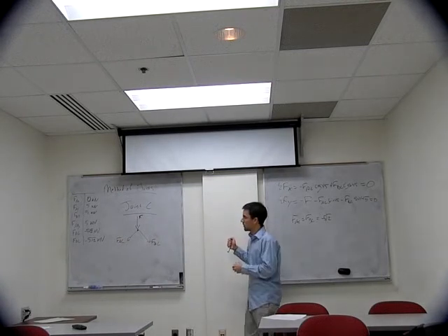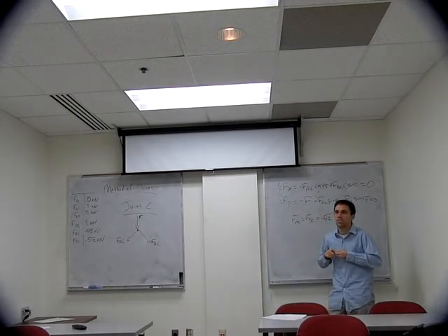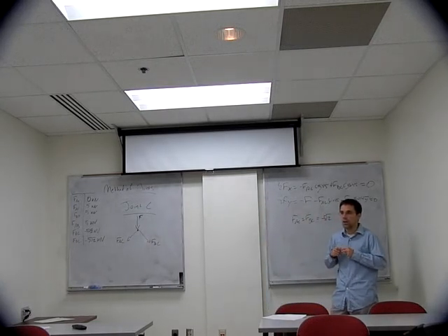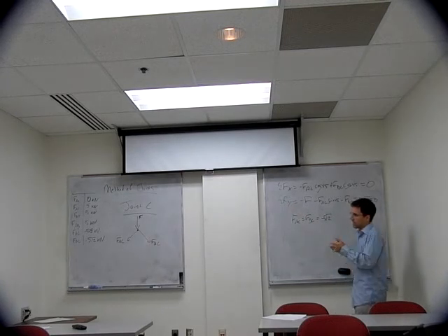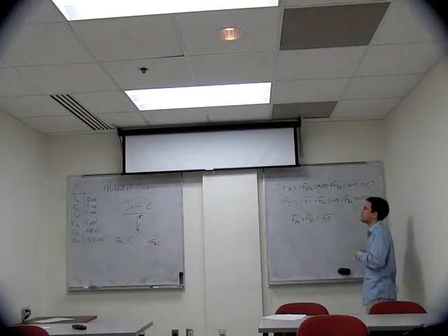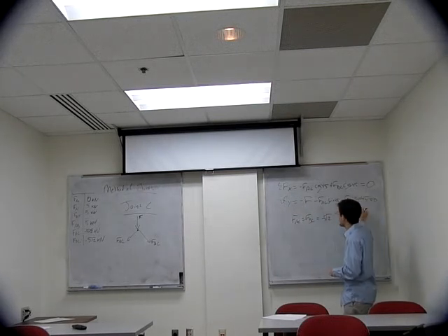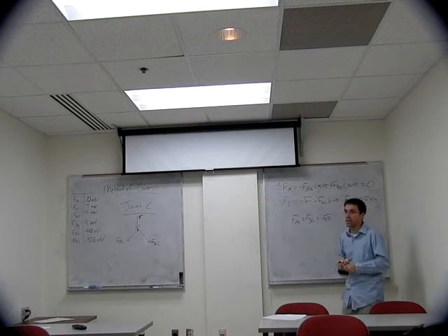And the reason that we were able to do that without using all of the summations, without using this last one and looking at joint P, is that we used that moment equation in the beginning. So that allowed us to not have to use all the equations, but that's not something you can always do. But what we can do is still use this last equation that we've already written out as a check for our numbers.